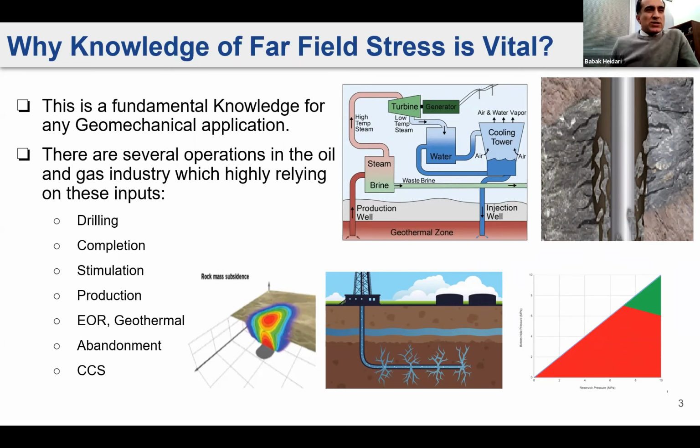You may question where in the abandonment stage geomechanics and this knowledge are going to help. For sure, if you want to abandon a well or a field, we put, for example, cement plugs, physical plugs, and these plugs need to stay intact over the course of, for example, a decade.